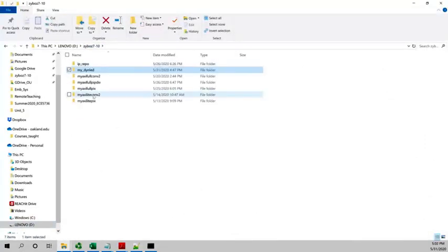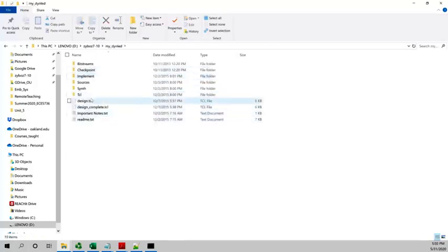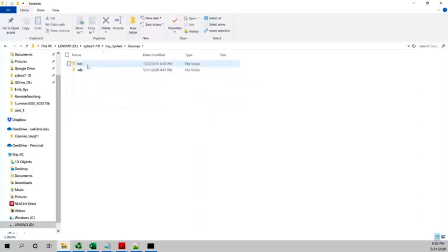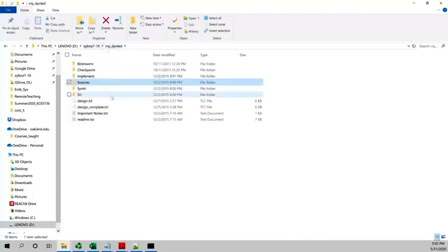So I downloaded, like I said, a zip file, right? And I unzip it here, my file structure. And of course, remember what I did a moment ago, right? I actually replaced the top IO XDC for my ZYBO Z7. But I need to now navigate to this folder.